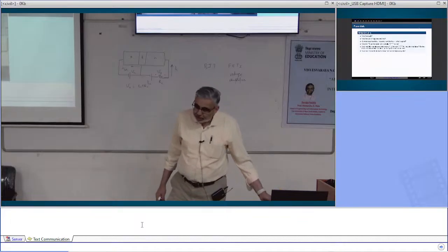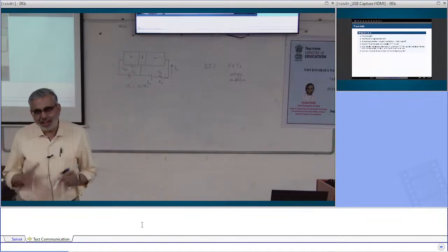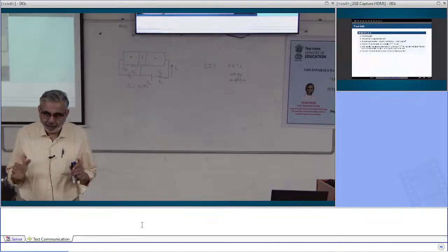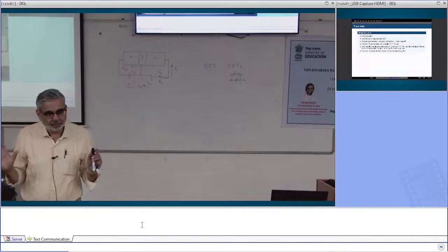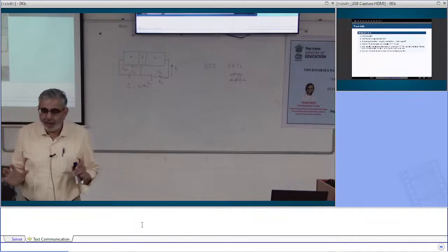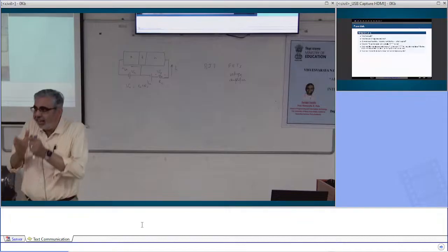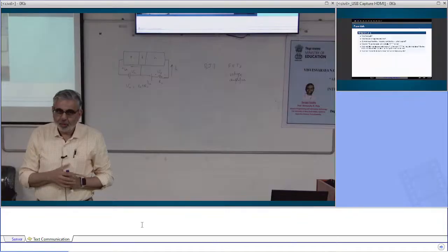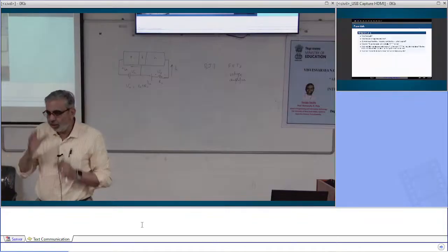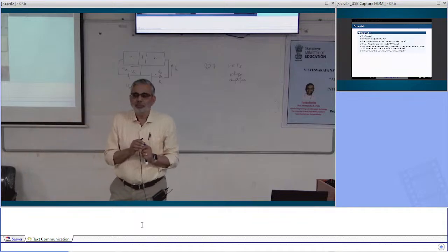आपने बीटा किया तो आप गए. If you say, the reason I say is this, because beta varies so much. Unless your design is independent of beta, that design will never work. अगर आपने डिजाइन में कहीं भी बीटा का काम लिया है तो आपकी डिजाइन काम नहीं करेगी. You have to design and then check that for this range of beta, my design works or not. You cannot have beta as a part of your design process. Only beta is a check that whether my design will work or not. Okay, so now,